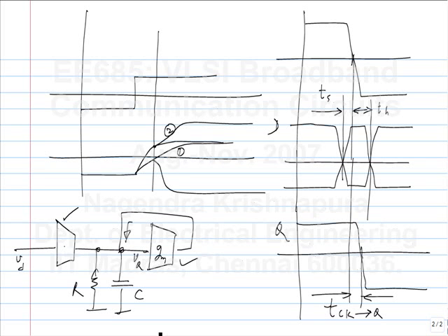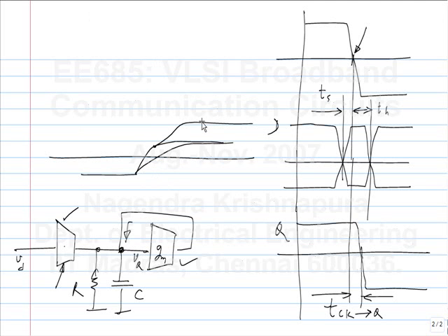As you switch the clock, even after the clock has crossed the 0 point, there is some current flowing through the input differential pair. So the input will contribute to the output. If it changes polarity, and if the initial condition was small, it could flip the polarity, and regeneration starts again. Regeneration is going on. It will go on after this completely switches off. If the polarity has accidentally turned around, then it will latch the wrong value. Okay. Clock and clock bar. What happens if there is a...